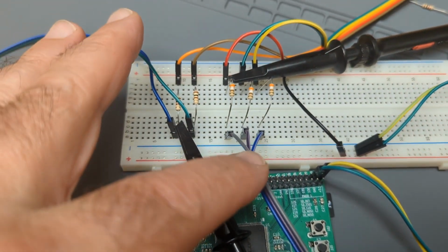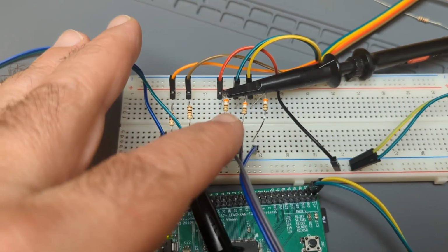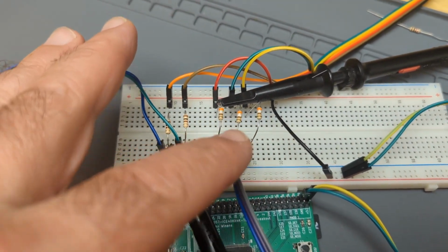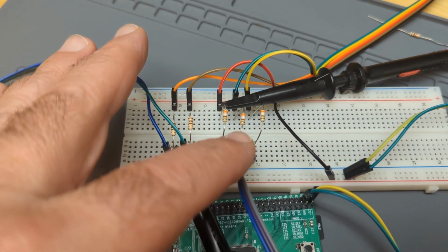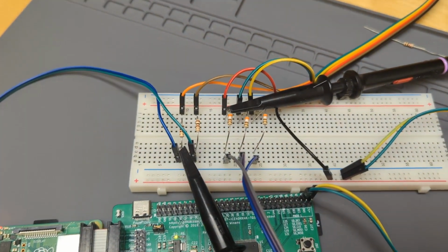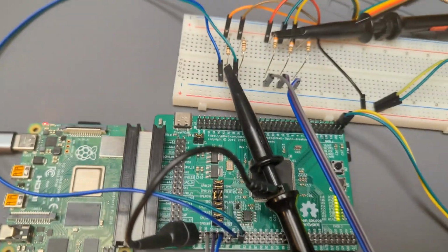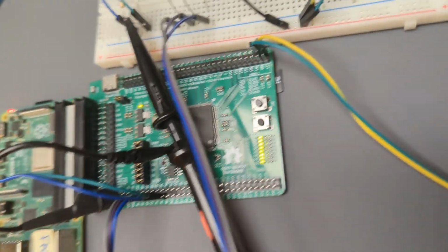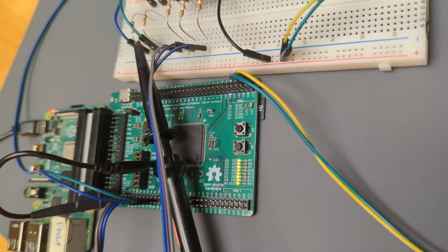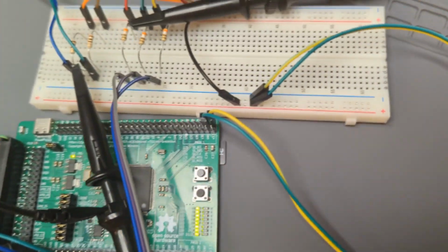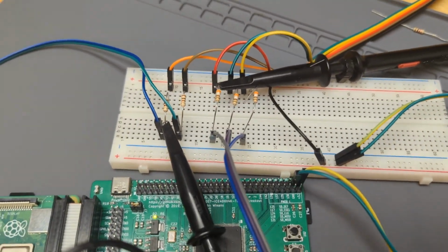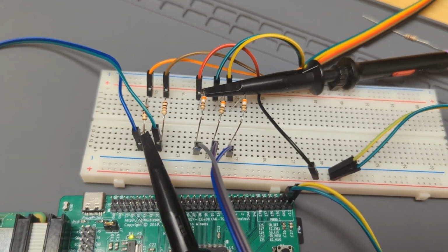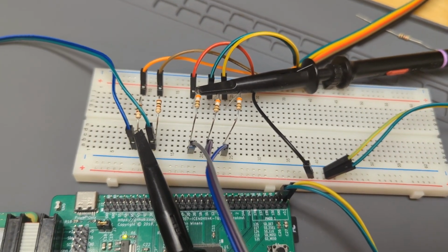The RGB values come out on these wires here, and they go through these three resistors. These are 390 ohm resistors, and the reason I chose 390 is because this particular FPGA, the iCE40HX FPGA that's in there, which I can't show because the wires are in the way. There it is. Hello, Mr. FPGA. This can only drive 8 milliamps per output pin, and I did not want to exceed the value.